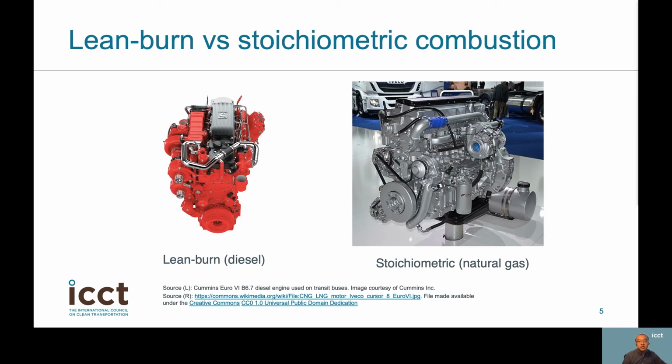A rather complex aftertreatment system is needed to control for these emissions so engines meet the most stringent emission standards. This is part of the reason why so many older diesel engines are considered high polluting. Thankfully, with adequate in-engine and after-treatment emission control technologies, both types of internal combustion engines are capable of meeting Euro 6 or EPA 2010 emission standards and can be considered soot-free.